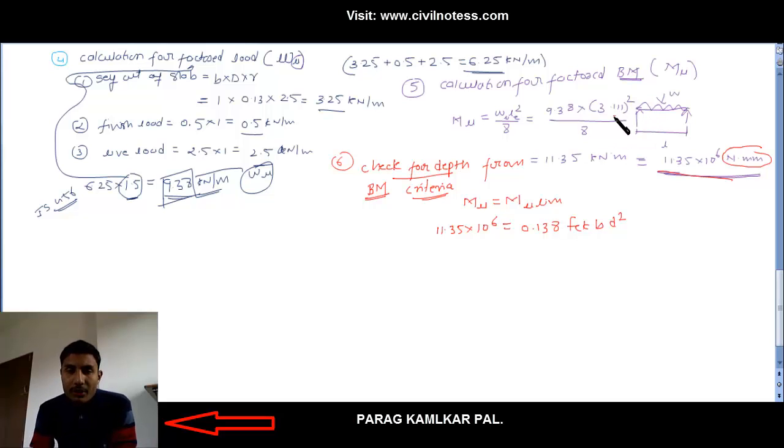We take some depth, 111, which you have seen over there. This is not the depth, this is the effective depth. So we take a depth of 111 mm, which is the effective depth. We wanted to compare, and from this we are going to define this effective depth also. When we get the required depth, we compare it with the depth coming from the calculation, and only then can we assign that this depth is the required depth. What we take is 111, our design depth. We are going to design for that 111, but the requirement is different.